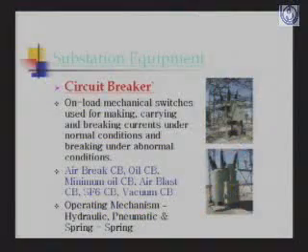What is the function of this gas in the circuit breaker, likewise oil or air blast? It is an insulating medium because the arc generates a lot of heat, and to dissipate the heat we require an insulating medium inside the circuit breaker. Oh, not conducting, actually insulating. I mean this is just to dissipate the heat absorption in the circuit breaker. The operating mechanism of the circuit breaker can be hydraulic, pneumatic or spring type.